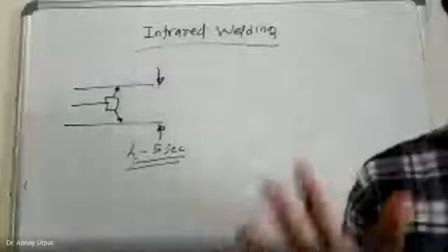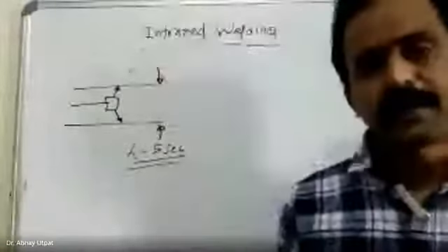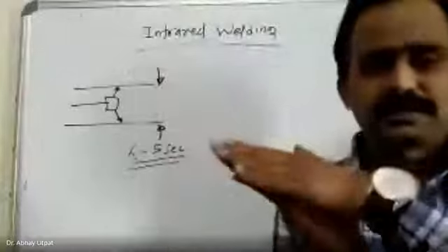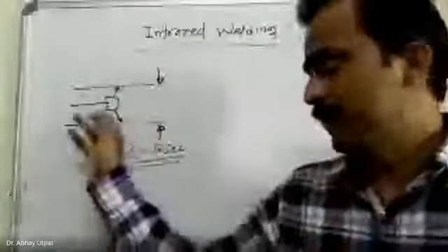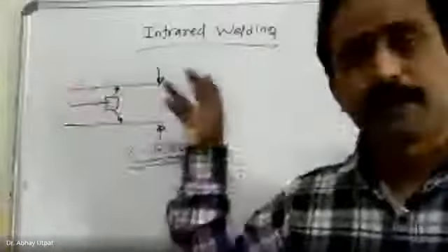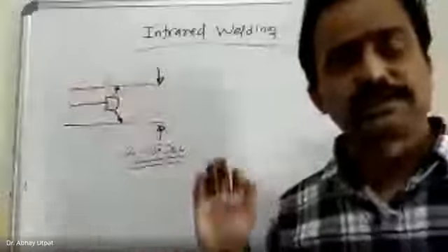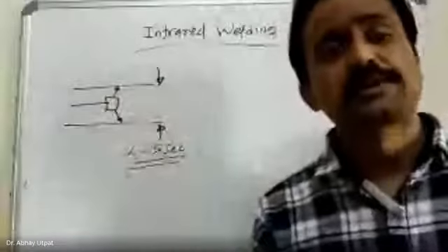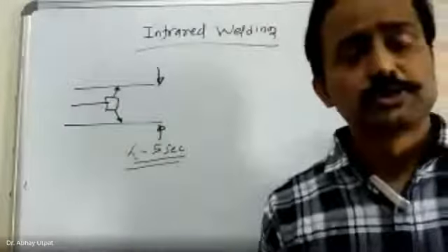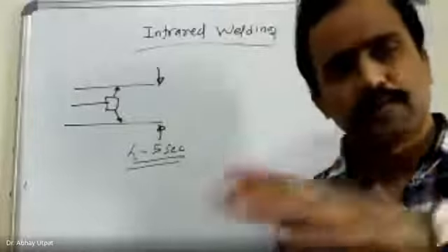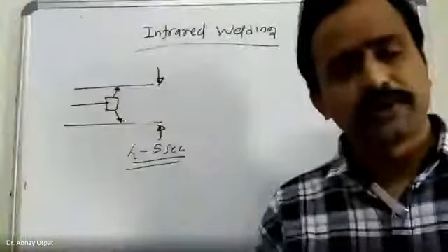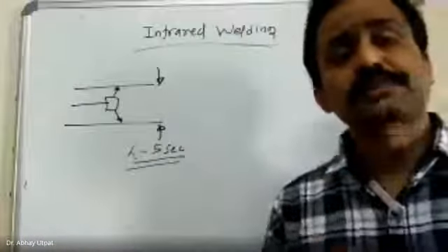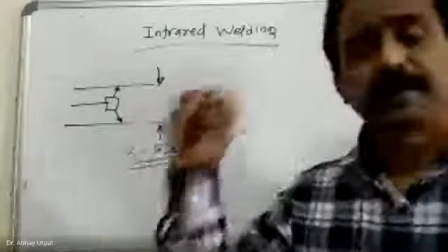So I repeat once again, it is very simple to understand. Infrared source is used between two mating surfaces. Precise time and controlled infrared radiations are applied. Once you apply it, you can produce the joint in 4 to 5 seconds. This is usually used in precise areas like aeronautical industries. Structural reliability is higher than other sources. It is used usually for some fluid tanks, some door strips, then some other tanks and pipes which carry fluid. Such applications, larger pipes, are for infrared welding.